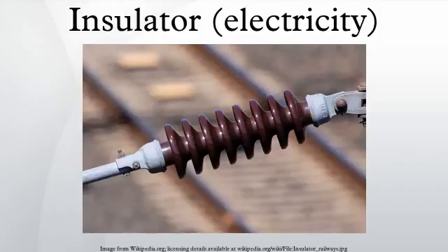Class 2 insulation means that the device is double insulated. This is used on some appliances such as electric shavers, hair dryers and portable power tools. Double insulation requires that the devices have both basic and supplementary insulation, each of which is sufficient to prevent electric shock. All internal electrically energized components are totally enclosed within an insulated body that prevents any contact with live parts. In the EU, double insulated appliances are all marked with a symbol of two squares, one inside the other.